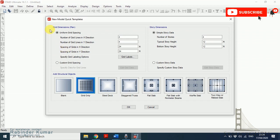Grid dimensions are categorized into two panels, uniform grid spacing and custom grid spacing. Uniform grid spacing is used when the size of the grid is the same in X and Y direction. Most of the time our centerline spacing is not constant along X and Y direction. Then we go with custom grid spacing. So click custom grid spacing and click on Edit Grid Data.